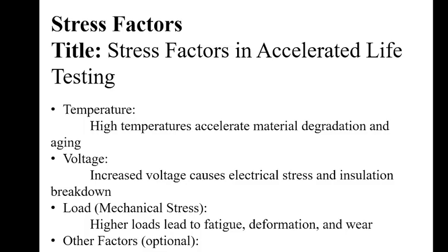In accelerated life testing, stress factors will be increased to speed up the failure process and better understand product reliability. Temperature is one of the most common stress factors, as higher temperatures accelerate chemical reactions, material degradation, and aging effects. Voltage is another critical factor, especially in electronic systems where increased voltage can lead to electrical overstress and insulation breakdown.